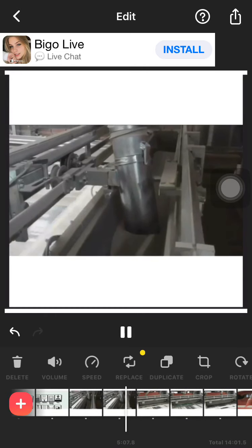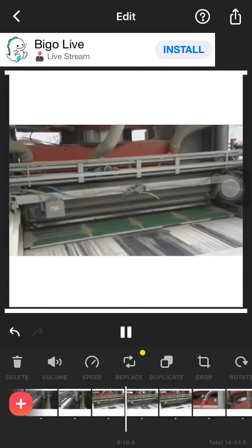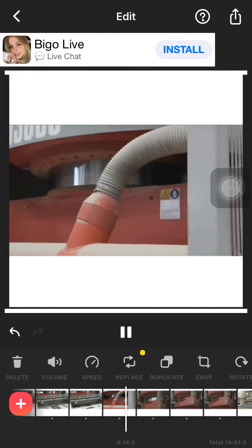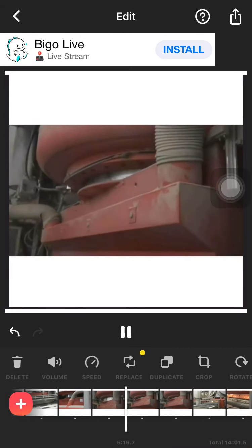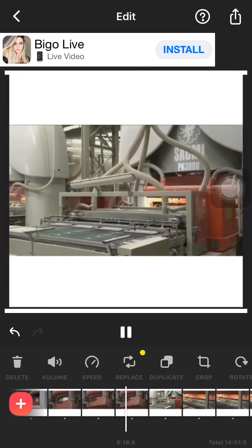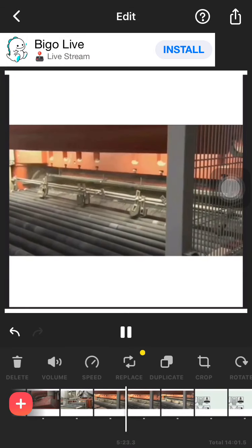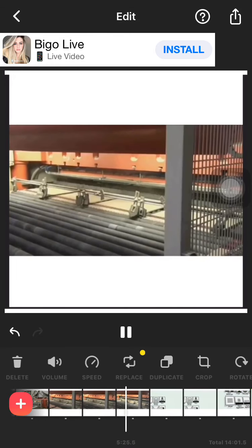The vat releases measured quantities of atomized powder into a tray, which distributes the powder evenly into the mold. A force of 340 to 400 kilograms per square centimeter is applied using a large hydraulic press. The combination of high pressure and residual moisture turns the powder into a solid mass.